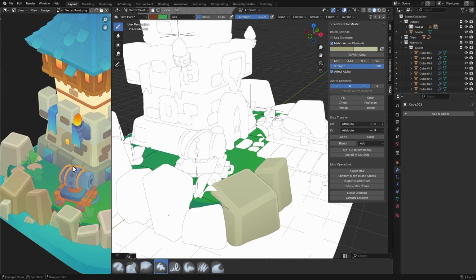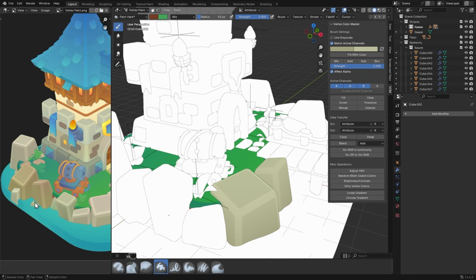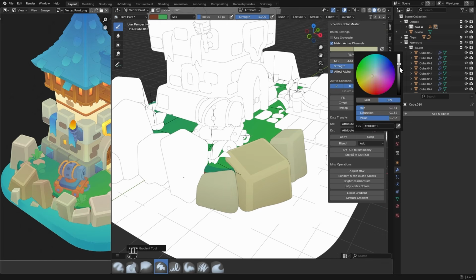If you wish, you can change the color of the entire object, thereby creating more variation. To do this, click on Adjust HSV, increase the saturation, change the hue, and make it brighter or darker. The more variations, the more natural it looks. This makes the image look much more interesting.